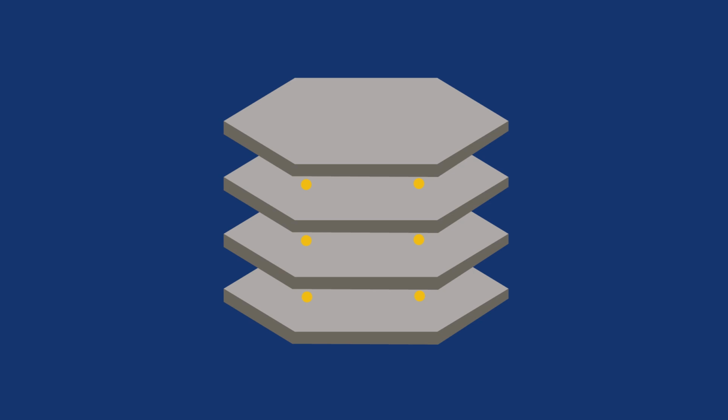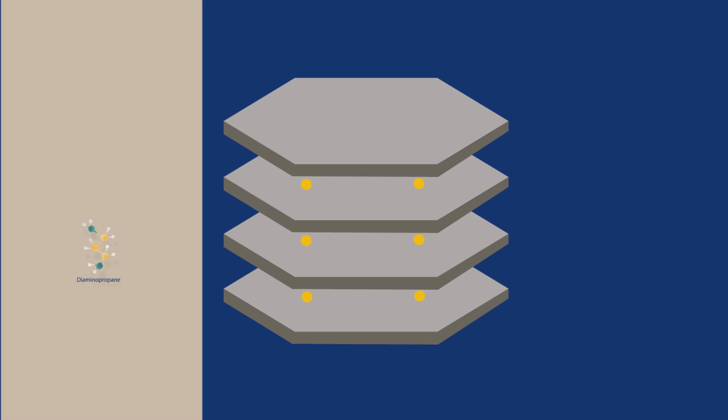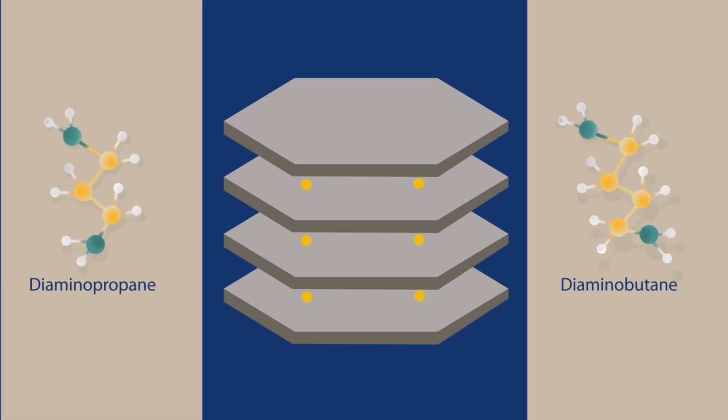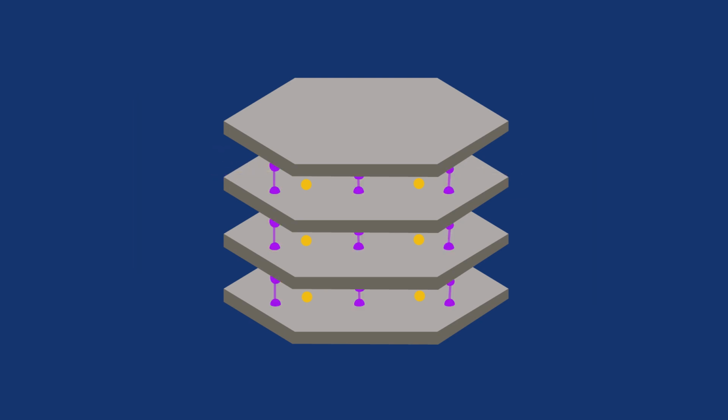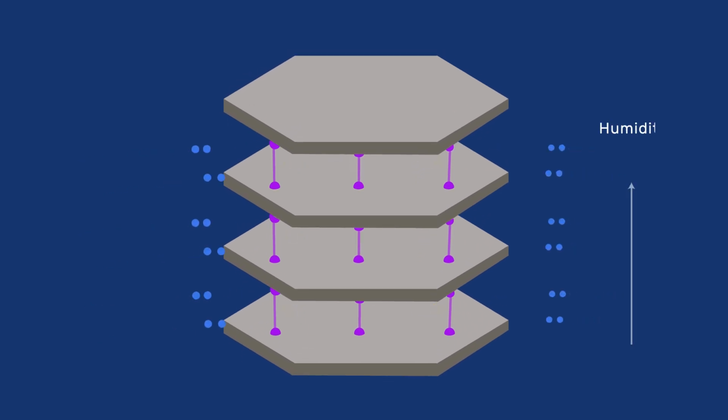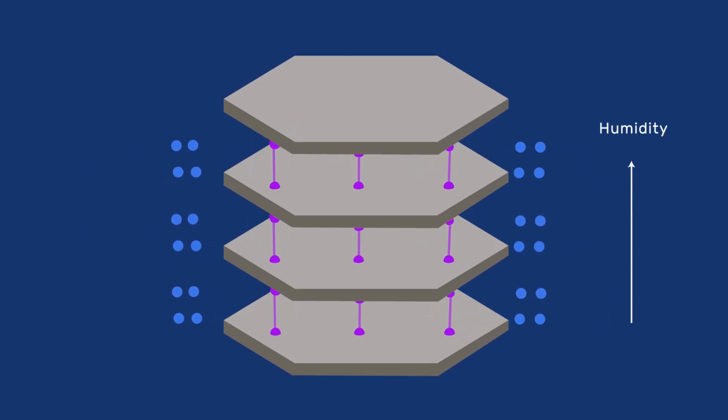Compounds found to be effective in this are diaminoalkanes such as 1,3-diaminopropane and 1,4-diaminobutane. They are believed to intercalate between the clay platelets connecting opposing surfaces. This prevents water ingress and thereby cancels the swelling and shrinkage that these stones suffer otherwise when humidity changes.